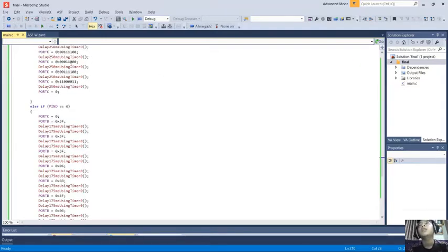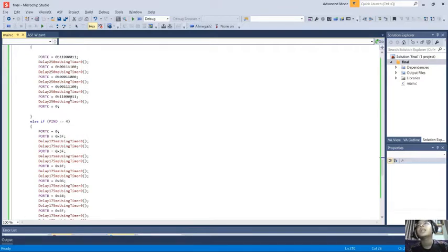After that, bits 3 and 4 will turn on and the others are turned off. And after that, bits 2 until 5 will turn on. And the last one, on port C the LED bits 0, 1, 6, and 7 will turn on. And the last one, the LED port will not display anything, as we assign port C equal to 0.